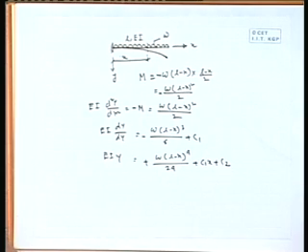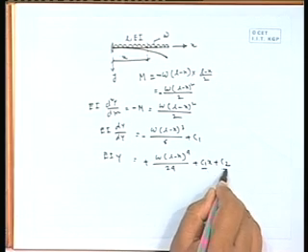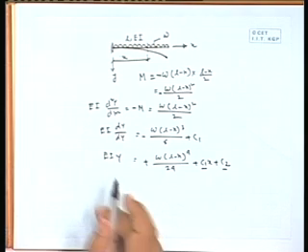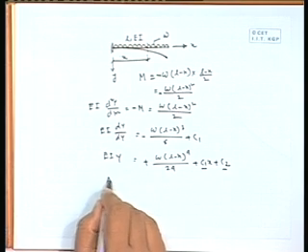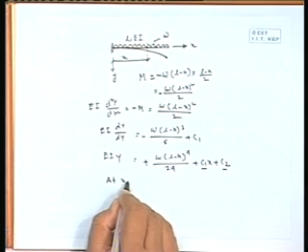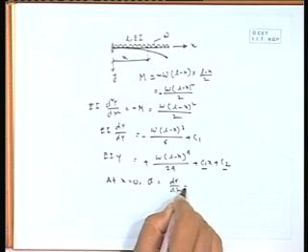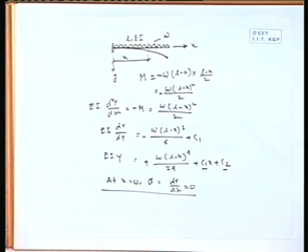Once you have that expression, our job is to determine C1 and C2, these unknowns, through boundary conditions. It is in the same manner: at x equal to 0, theta or dy by dx equal to 0. So, this is the first condition.